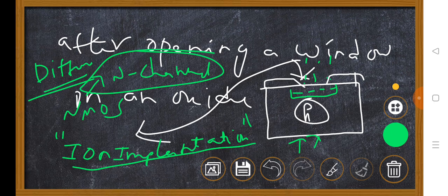That means gate oxide, growing a thin oxide. After that, you should perform CVD. Then after CVD, you should perform diffusion once again. After diffusion, you should create contact cuts. After that, metallization. The remaining steps are the same as usual. The only difference between enhancement mode and depletion mode NMOS is that in enhancement mode we do not have any channel in the fabrication process, while in depletion mode we have a channel. The only extra step is ion implantation, after opening a window in an oxide.